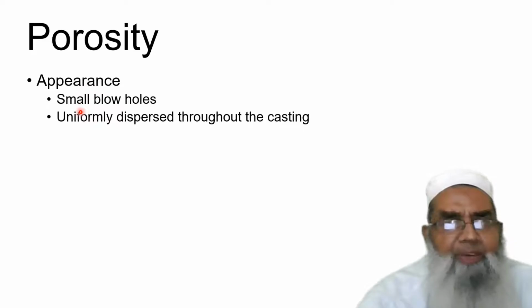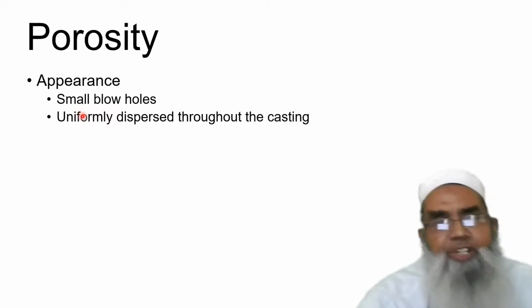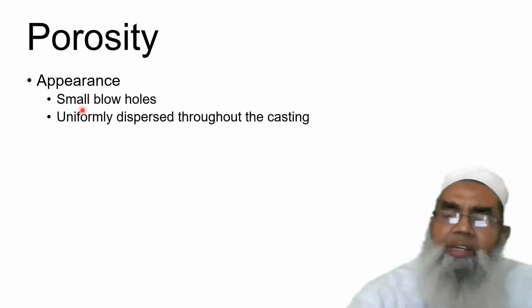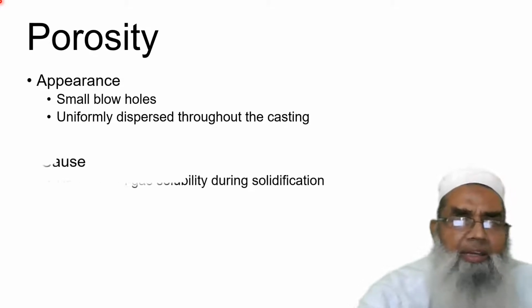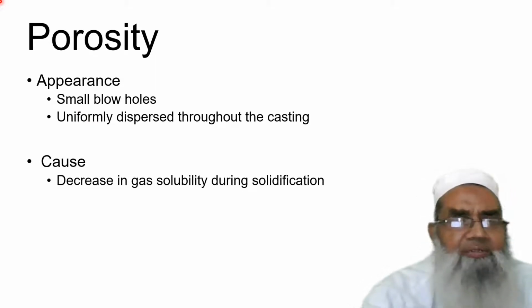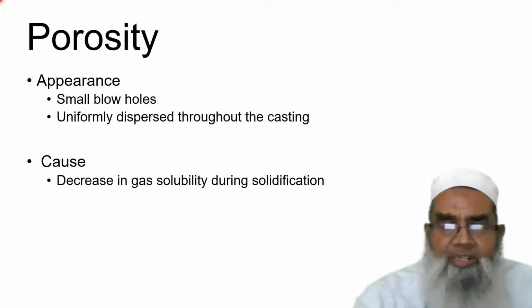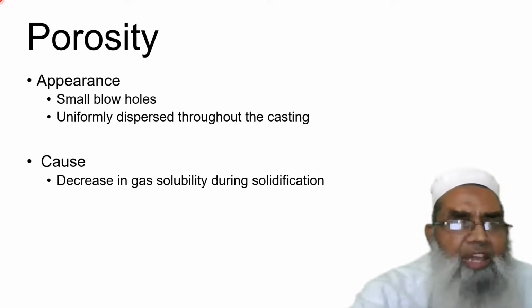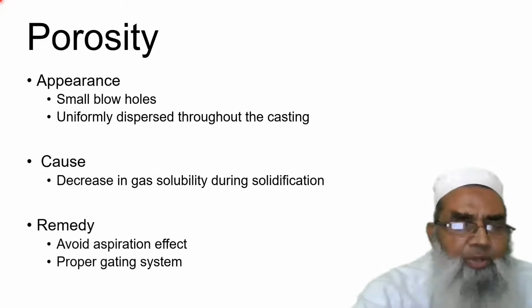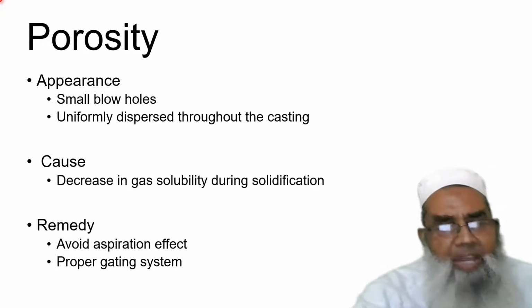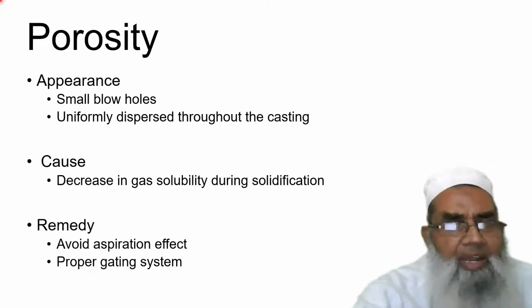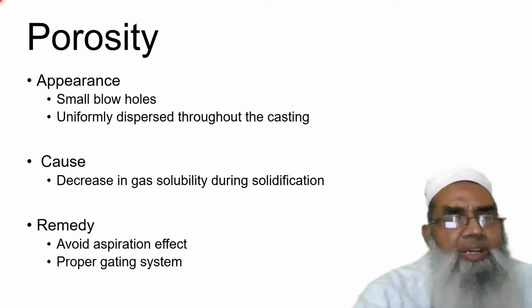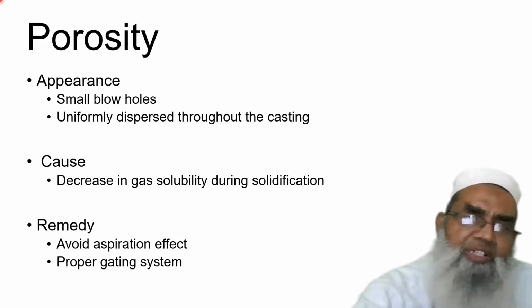The same type of thing, but when it is distributed throughout, we call it porosity. The causes may be a decrease in gas solubility during solidification, and keeping that in view, by avoiding the aspiration effect and designing a proper gating system, we can overcome this porosity.